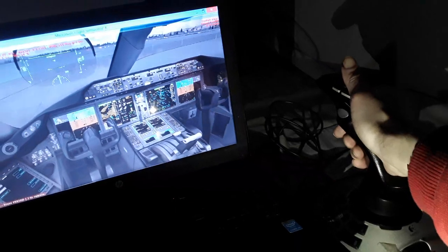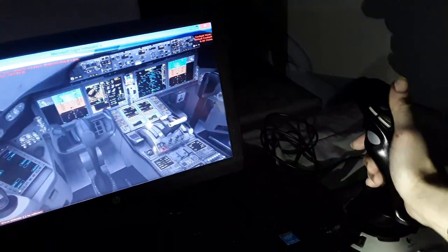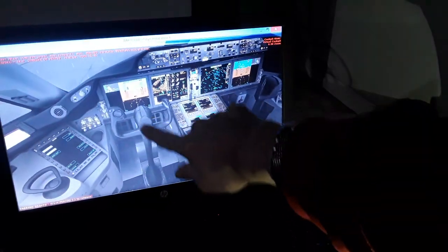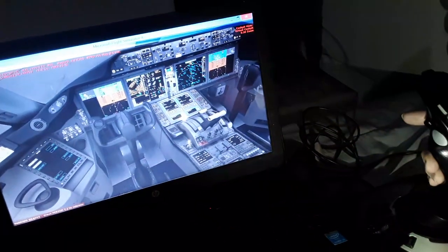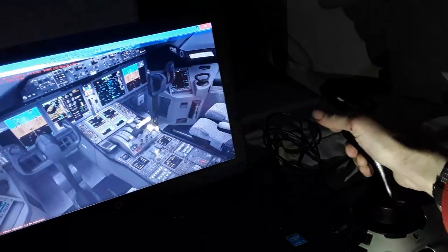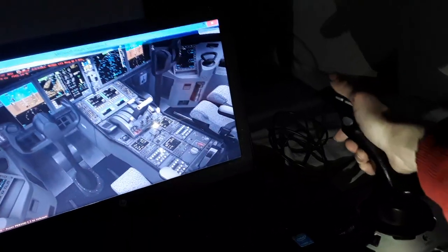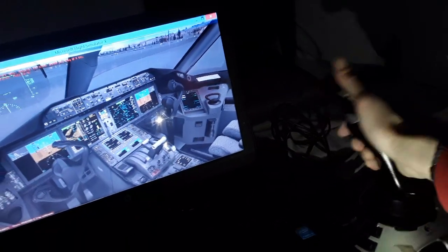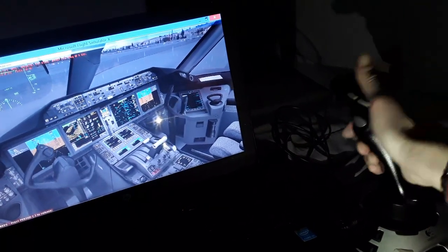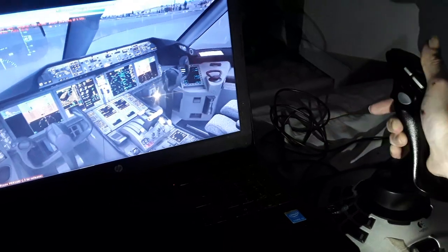So you can see again climb and descent. We have the control column for climb and descent. This section of the yoke, the control column. Moving up we climb, moving down we descend, around the lateral or pitch axis of the aircraft. This way is the longitudinal roll axis, the control wheel, or the side stick left and right.